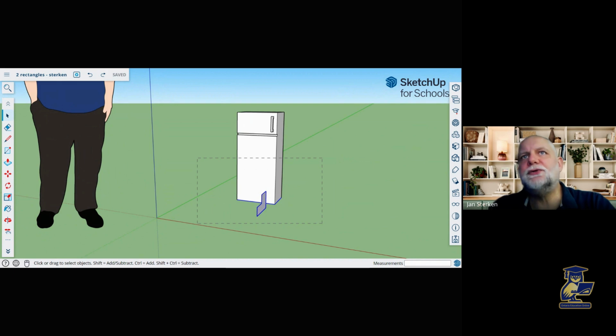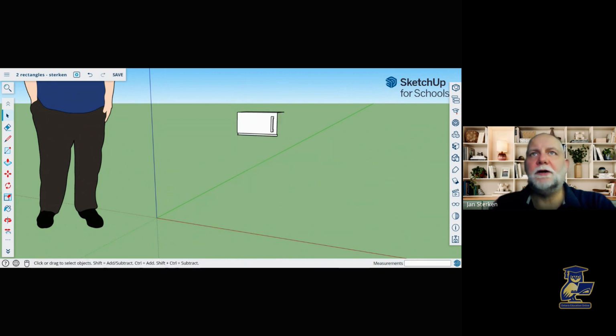So the 2-3 vertical lines right now that we see the fridge touching, when I let go of the mouse, you can see that was also selected. Okay, so the selection tool has two modes. From left to right is a windowed mode, which selects only things inside. And from right to left is a crossing window mode, and that does everything in the window plus crossing the window. Okay, and so now I could just press the delete key on my keyboard.